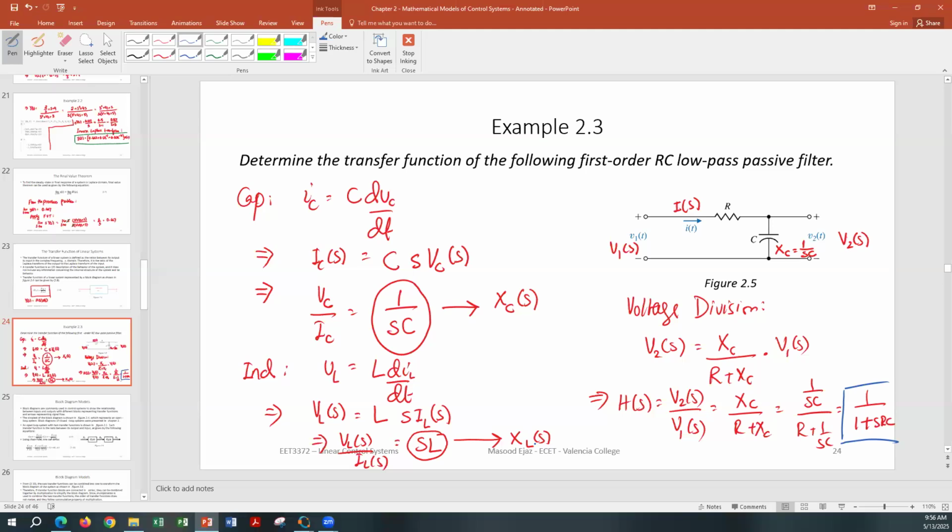Laplace actually is a superset, because we discussed the exponential response of a circuit, the transient response, and we discussed the steady state sinusoidal response. Laplace combines both. When you solve a circuit in the Laplace domain and then go back into the time domain, it shows you the steady state value as well as the transient value. So it combines both things.